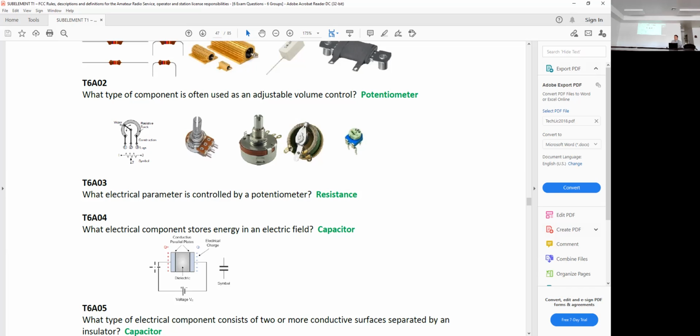Well, remember when we talked about inductors, how you can get magnetic energy out, or you can take energy in? That's what's happening. You've essentially got a motor, and when you turn the motor backwards, it's generating electricity and putting it back into the battery. Oversimplification, but that's the concept. Race courses are all tested that way now. Yeah, why throw away energy? The biggest problem with an electric car is the battery, so what do you do to supplement that a little bit? Well, don't throw the energy away when you're stopping. Save that for later.